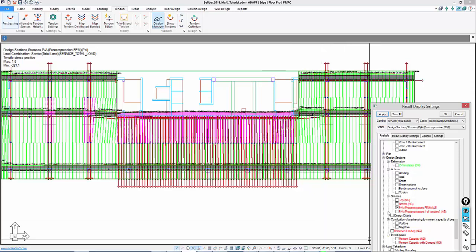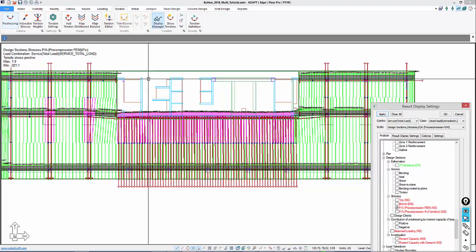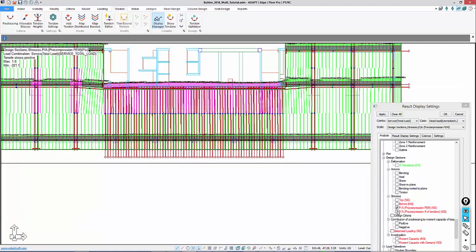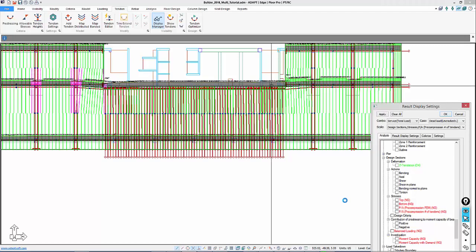So if you're going to use this FEM option, you need to make sure that the wall to slab connections and the support conditions allow for the slab to shorten freely so that it mimics, again, real life conditions for the transfer condition of the force into the slab for the PT. A lot of times you're going to use this number of tendons option just as a bypass, knowing that you're going to detail it, allowing it to shorten freely. So that's what the two different options are.